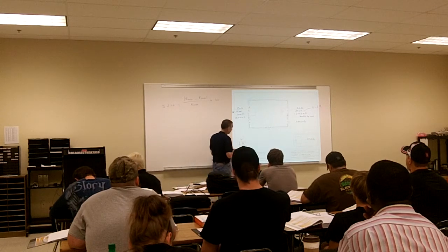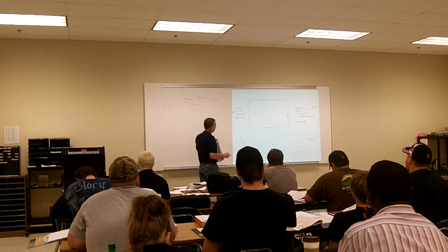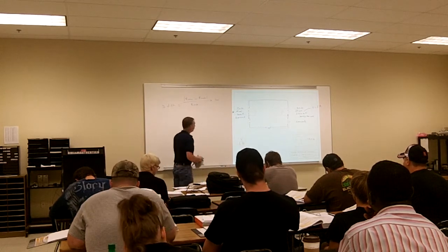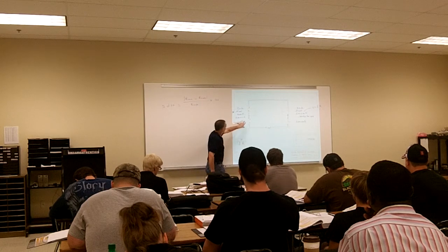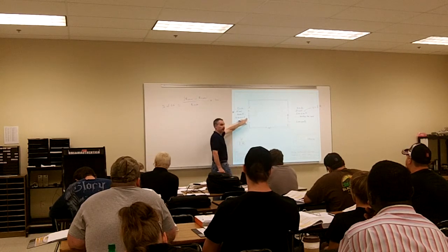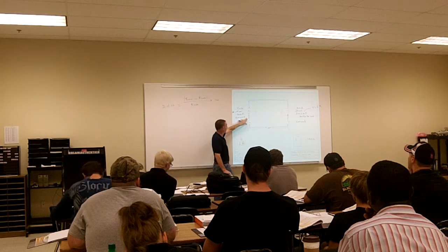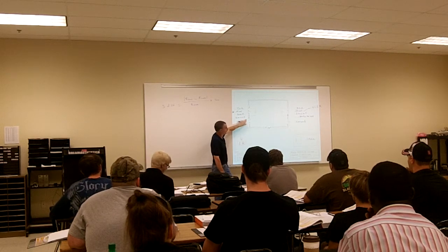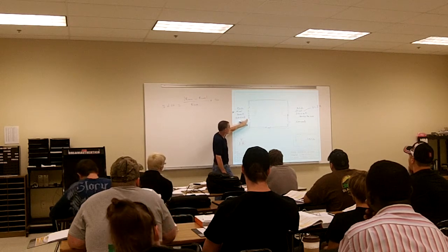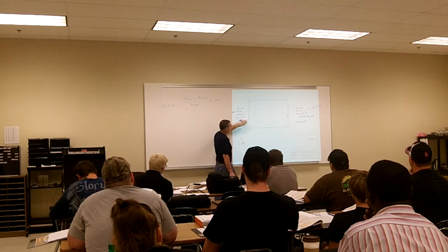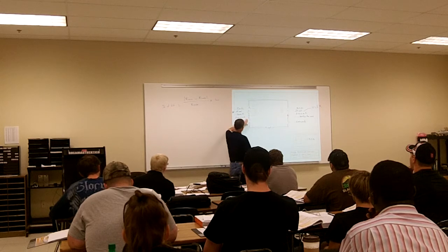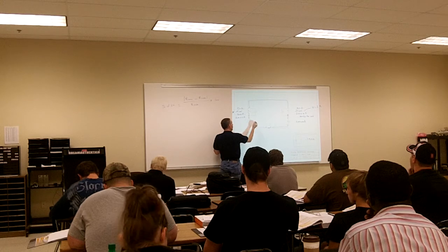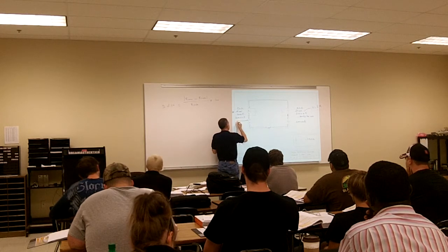So what I'm going to do is, we could do one of two things. We can either check it with a voltage meter or we can check it with a current meter. Well, a lot of times we can't shut the machines down. If we're working on an automation line or something like that, they don't want us to stop production. They'll find people to fill in that one section of that station that's down, and they'll just have people take them off the line until we get it up and running. So they're not going to let us shut it down. So we always have to use our voltmeter a lot of times. So what we're going to do is we're going to put our voltmeter across our fuse.